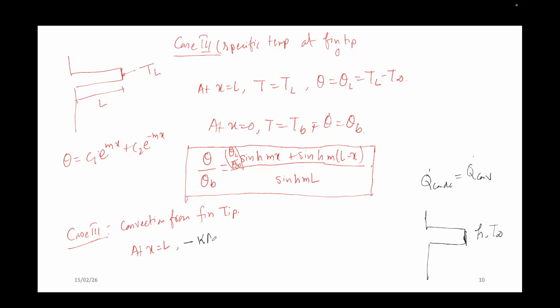Minus K A dT/dx at x equal to L, equal to h A C (T L minus T infinity). This temperature is TL. So this is the boundary condition.